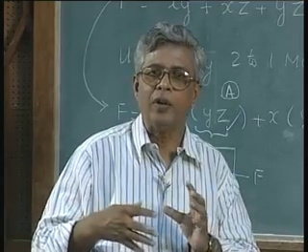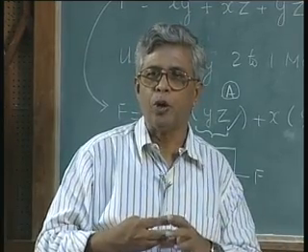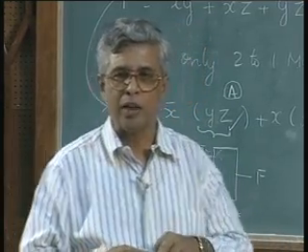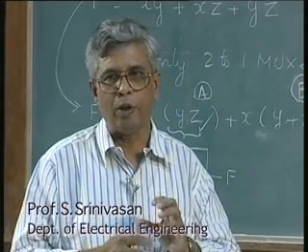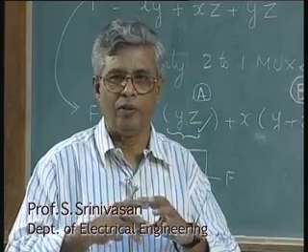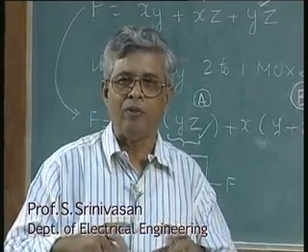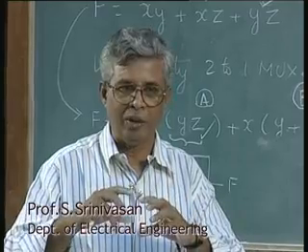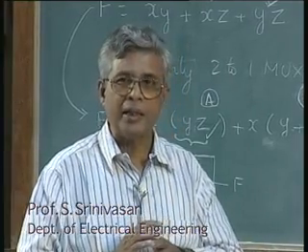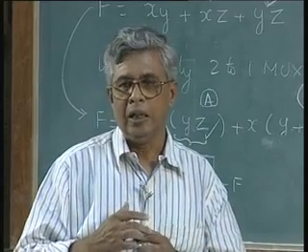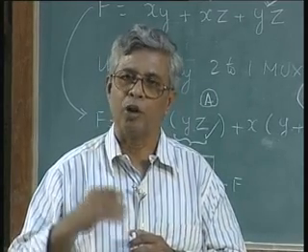A huge function will be given with several inputs and several outputs, there may be several functional blocks with a variable number of inputs and outputs, and all of them should be mapped onto a uniform hardware where a uniform type of functional block is available, and that will be used for synthesis. We will stop with this, and tomorrow we will see how to do the same type of implementation using programmable logic devices.